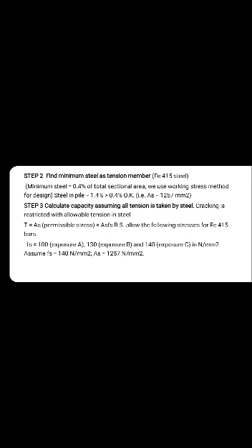Now calculate the tension. Allowing no cracking of concrete, that is Ft is equal to Fck by 20 by limiting tension in concrete. Ae is equal to Ac plus (m minus 1) into As. m is equal to 280 by 3 sigma cbc, which is obtained as 13. On substitution, we will get 105,084 mm square, and Ft is equal to 1 Newton per mm square, and tension is obtained as 105 kilonewton with no cracking.